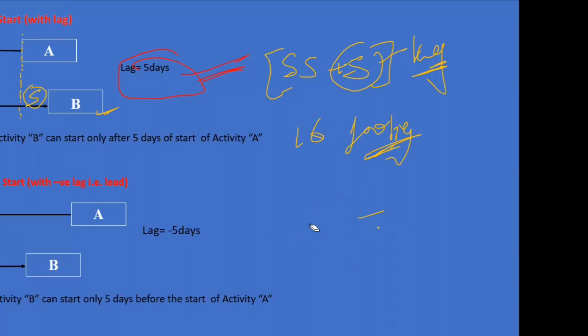What you do is the excavation in 3 or 4 maybe, and then you immediately start the PCC on those 3 or 4, and you continue the excavation with the rest of the footings. At that point, activities are scheduled start to start with some kind of lag, maybe 3 days, 4 days, whatever the condition may be. In the same way, negative lag also works.